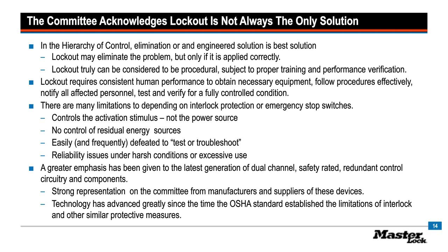And so the question of reliability is there, both in terms of human tampering, defeating, and how well they hold up to harsh conditions or repetitive use. For instance, an e-stop is designed to stop a machine in an emergency. It has a specific cycle life, and if it's the on-off switch every single day, every single week of the year, there's a point at which the e-stop may fail at a point where its true intended purpose, to stop the machine in a hurry, is put to the test.